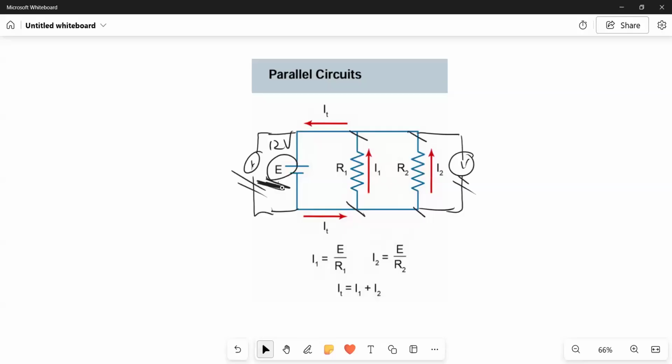And you will see how having parallel circuits is very useful when we go over to AC current, right? And the electrician in the class will tell you how parallel circuits are predominantly used in your house, with AC circuits. We're coming to that, right? So in a parallel circuit, when the resistors are arranged like this, the voltage from the battery shows up at the terminals of these resistors. However, the current through them, that's different.